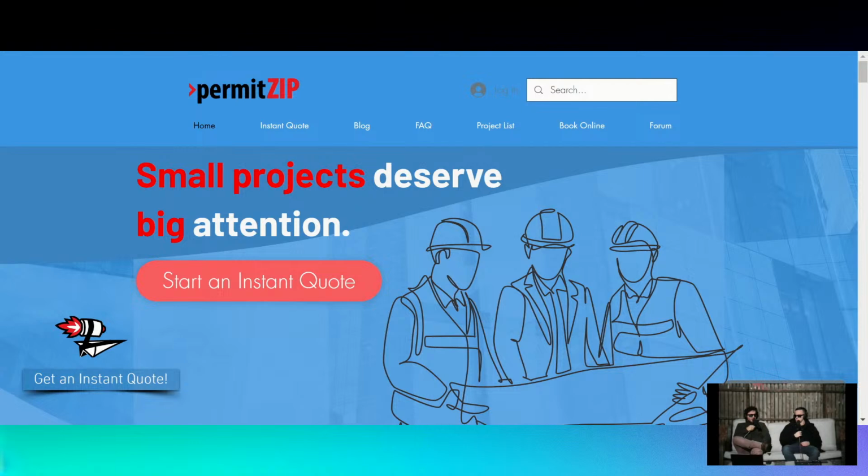So that's actually a good way to use them. Maybe you have a constant volume rooftop unit that's 10 tons and you want to put another 5 tons of mini splits to help give you some pseudo staging, then there's some use case there. As long as you don't have ventilation loads to deal with. If you can get them from natural ventilation, let's say, instead, or other hacks that can be done with bipolar ionizers, then yes, mini splits can be used to augment your load condition.